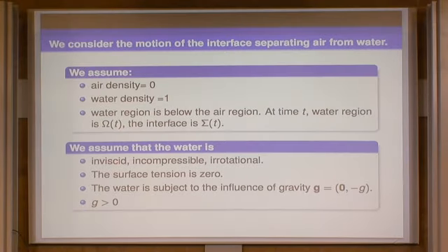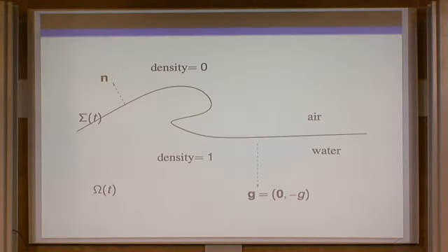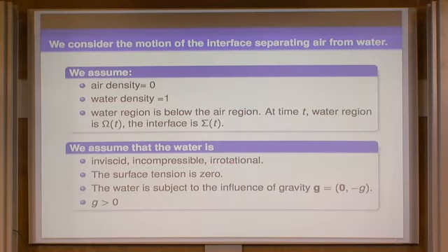We assume the fluid is inviscid, incompressible, and irrotational. In the middle of the ocean, in such an open field, the fluid is approximately inviscid and incompressible, so it's quite reasonable to assume that. Irrotational is indeed an extra assumption. I'm also assuming that there's no bottom, so really there's no boundary. For the fluid Euler equation, if it's initially irrotational, it will remain irrotational for all time. So this is valid for all time if it's valid initially.